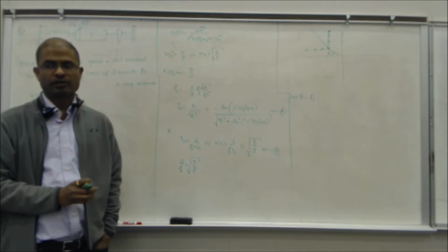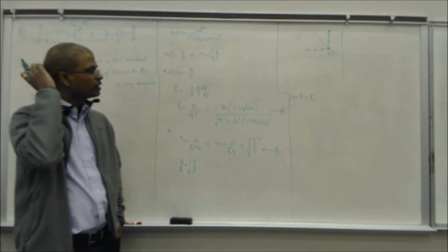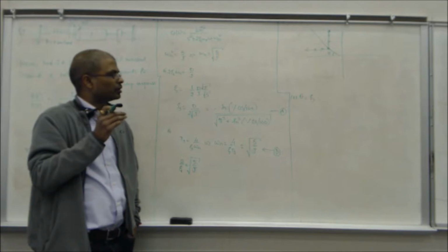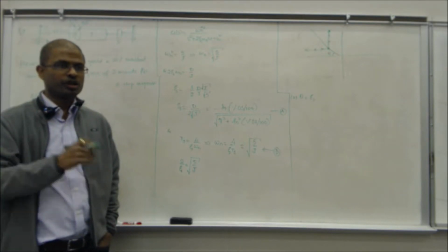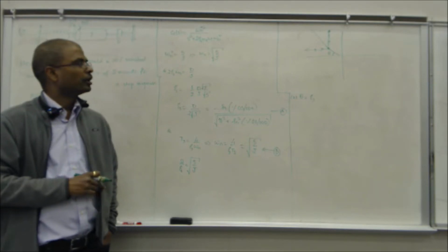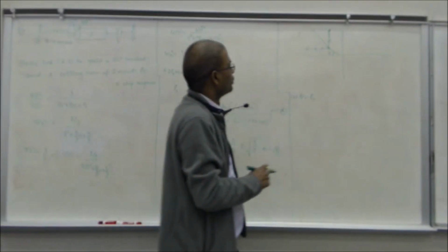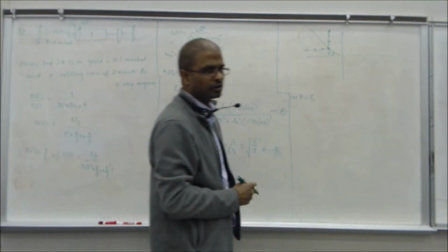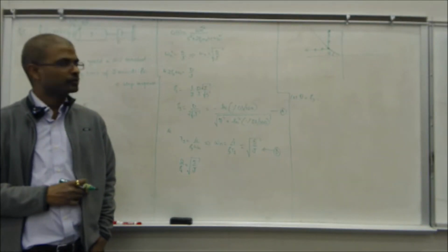As long as the theta remains the same, the damping ratio remains the same. That's kind of a linear relationship. Okay. As long as theta remains the same, the damping ratio remains the same, although you're changing the value of the poles, and you can impact this in the real world or in control systems.